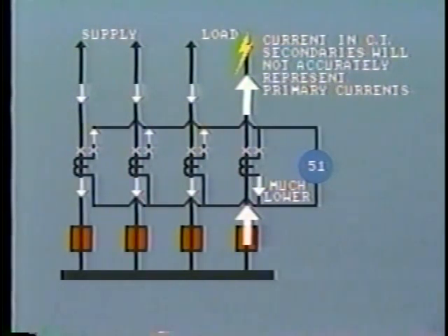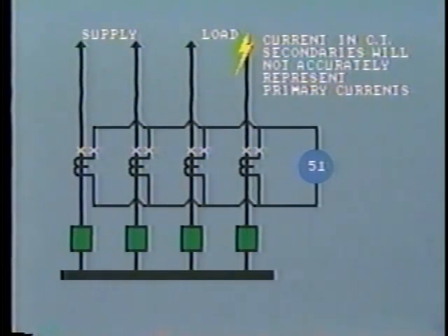The resulting imbalance would look like a bus fault and cause the relay to operate. This imbalance in secondary current is greatly exaggerated during the first 15 to 20 cycles of the fault. This is due to the transient that occurs in the primary current the moment it dramatically increases due to the fault.